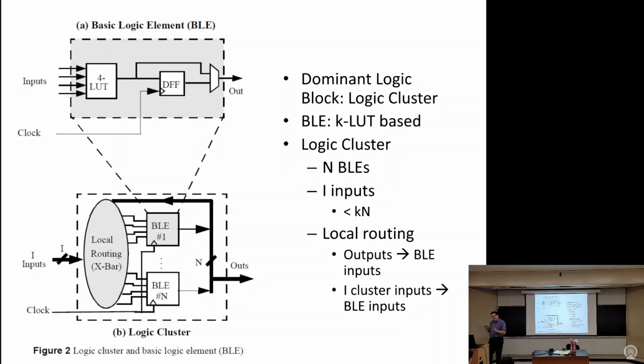So you have a little bit of hierarchy, and then the rest of it is constructed by replicating these logic clusters in a 2D grid and hooking them up with island style routing. And too much hierarchy would just cost too much. Is that kind of the idea? It's basically the things that we talked about before, that the long wires start becoming inefficient.